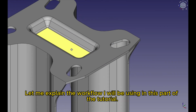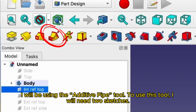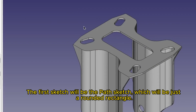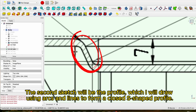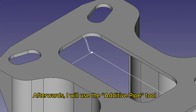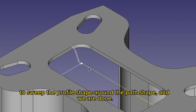Let me explain the workflow I will be using in this part of the tutorial. I will be using the Additive Pipe tool. To use this tool, I will need two sketches. The first sketch will be the path sketch, which will be just a rounded rectangle. The second sketch will be the profile, which I will draw using arcs and lines to form a closed S-shaped profile. Afterwards, I will use the Additive Pipe tool to sweep the profile shape around the path shape, and we are done.